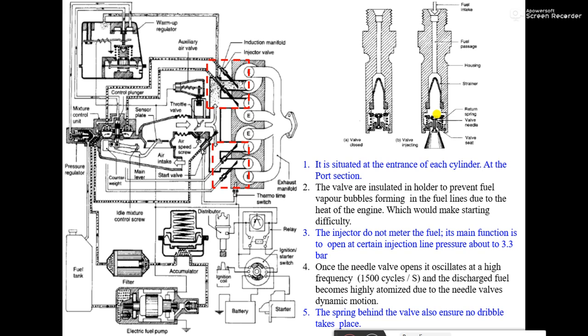So that is our requirement to make a combustible air fuel vapor mixture, okay. To have a complete combustion, our main aim is to make a combustible air fuel vapor mixture, okay. Vapor fuel mixture I am saying, so fuel should be vaporized. So to have a good or quick vaporization, our atomization is very important, okay.